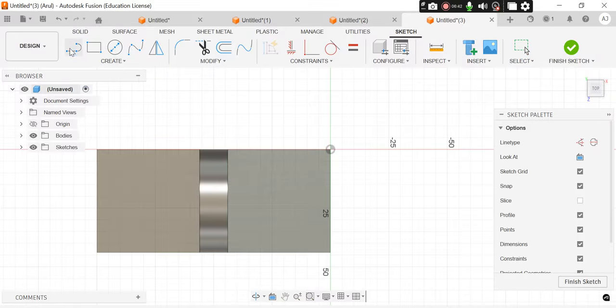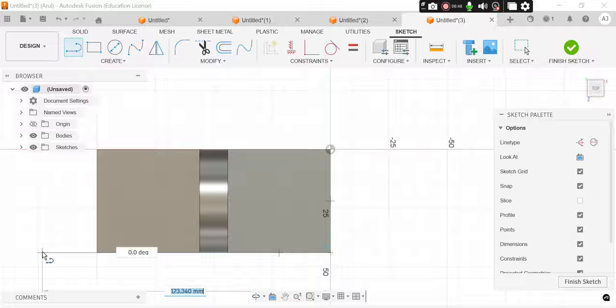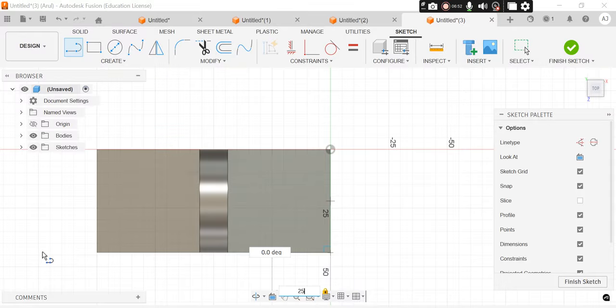So for that you construct the line. Select this end point. Horizontal gap for the line is given as 25. Select over the screen. Now dotted line is appearing. So press escape button. Once again give the line command.